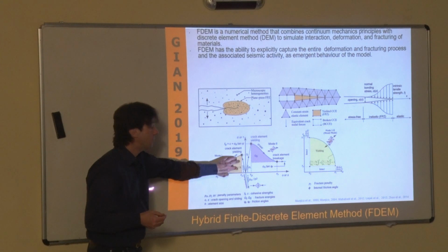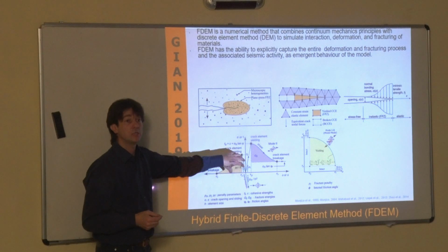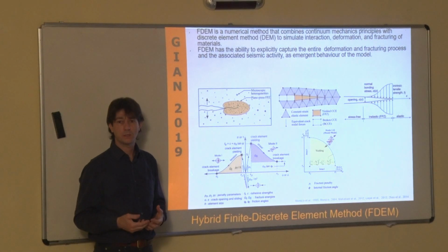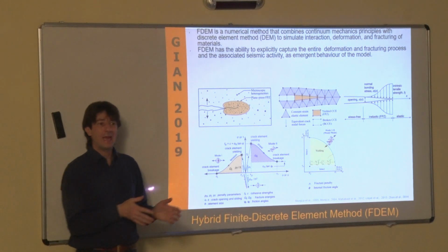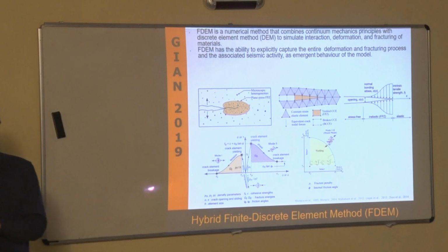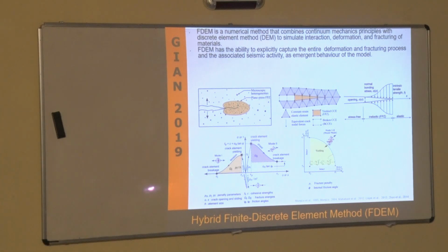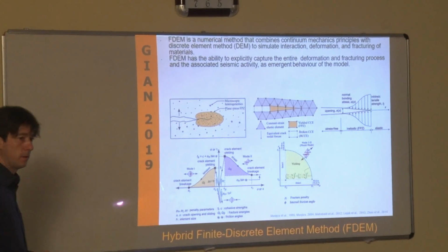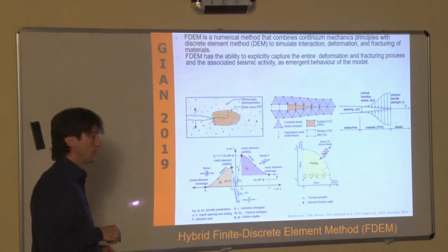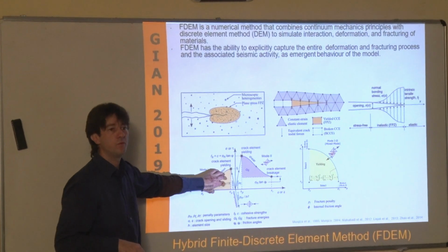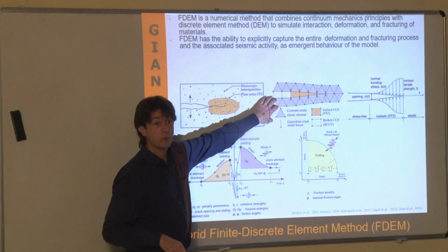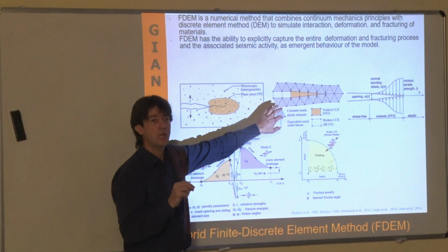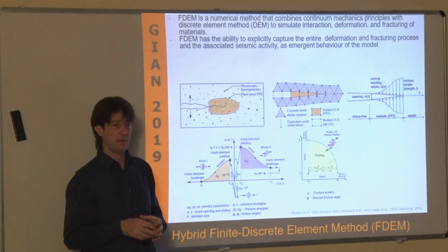The nice thing is that everything is related to the energy that is consumed during the process. So basically what you can do is relate this particular fracturing to the fracture toughness, the toughness of your material that you can measure. So it's not a non-physical property anymore, but it's a physical property. But at the same time, this is micromechanical because we are looking at a very local, small scale.